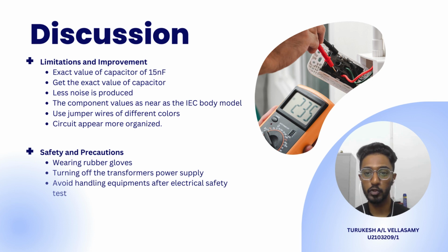The need to use 3 capacitors and other electronic components may produce more noise. To overcome this limitation, it is advisable to purchase the exact value of capacitor for the self-designed measuring device. As a result, less noise will be produced and accurate readings of measurements will be obtained.